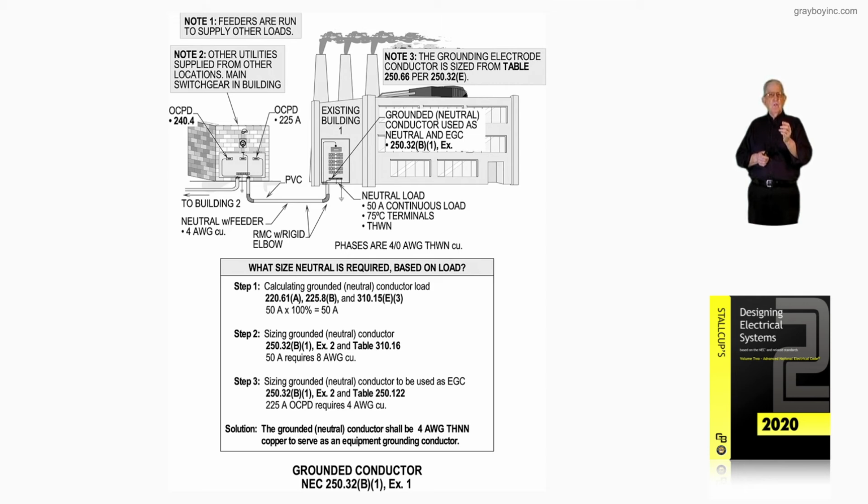Do you have to do it? No, you do not have to use the exception. You could take 50 and 125% as the designer or electrician or contractor if that's what you want. But I go to 100%. The exception allows that. So it'd be just number 8.